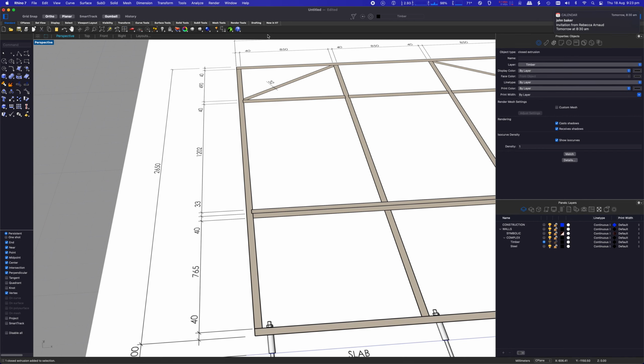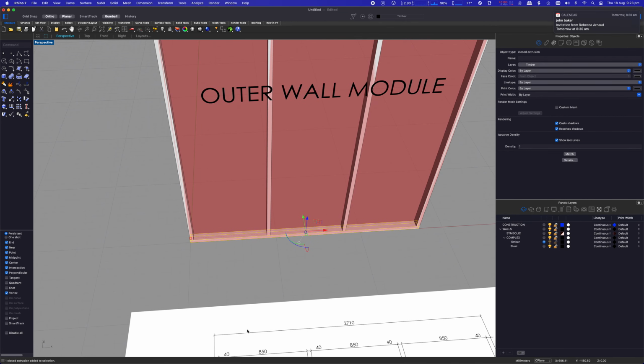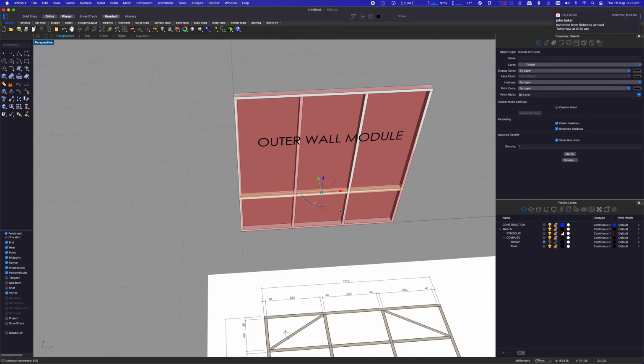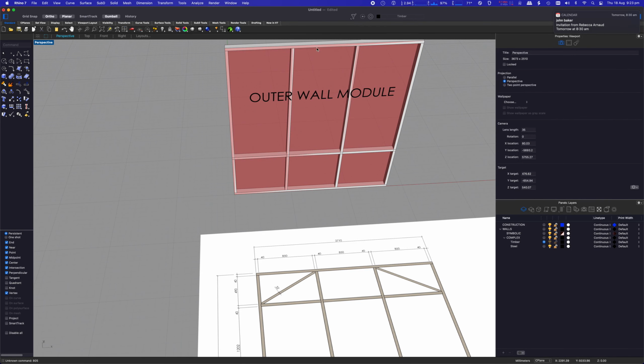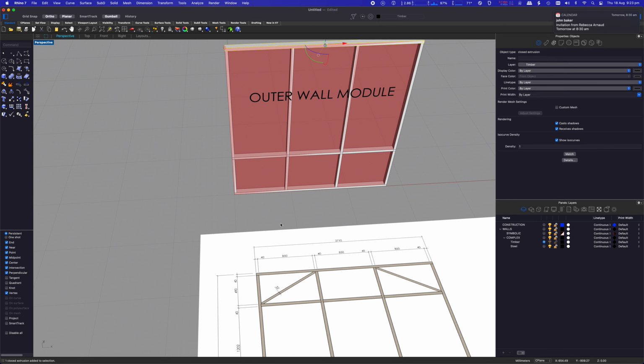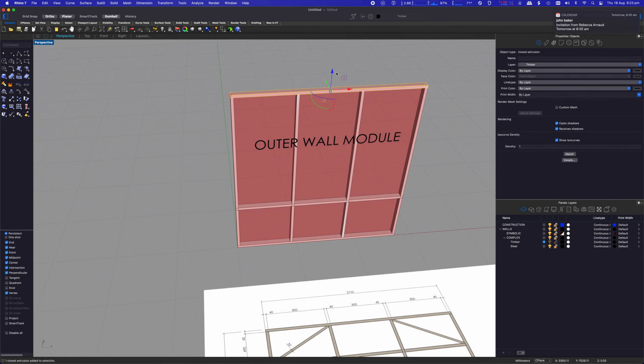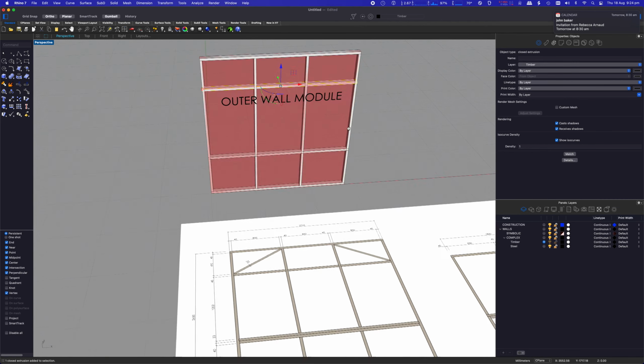765 plus 40 is 805, 805. Whoops. Don't. 805. And then there's one that is down 490 from the top. So again, hold down Alt, click that, and this time we want to go down, so we put minus 490 plus 40 is 530. And there's that.